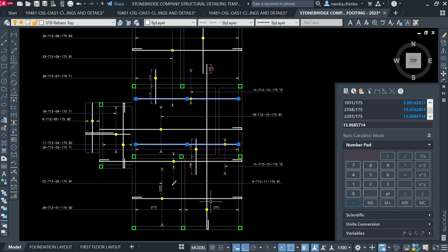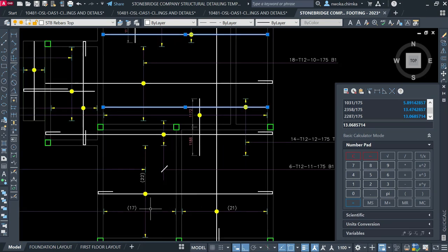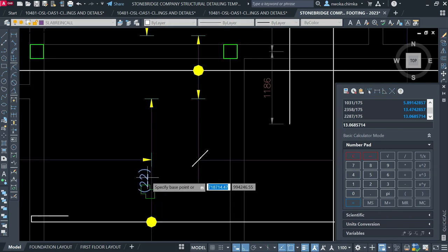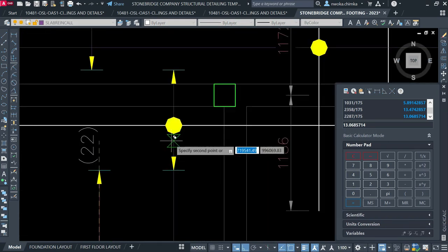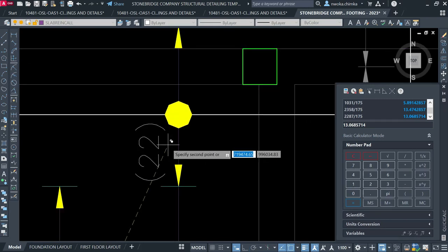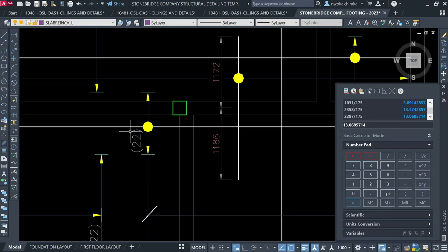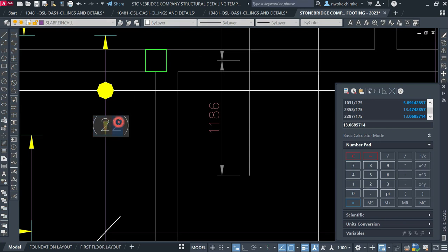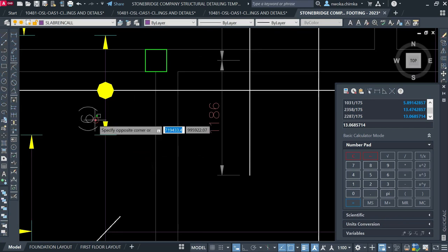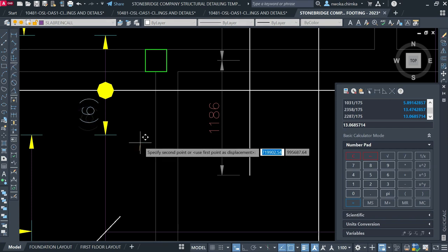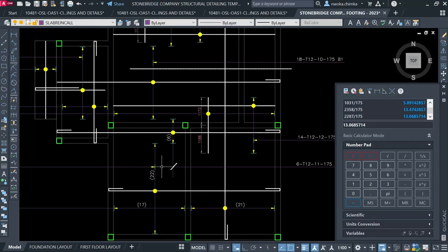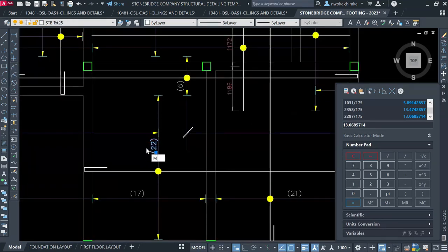So right now let's begin to put in these values, which is the bars running in that area. It's always good to put it around the bars so that it can be read very fast on site. I'll put this one here, and this one says how many numbers, which is 6. So I'll come here and put inside here 6. Okay, I'll put this here and then put this here. That's fine. So again, this other one here, where's the bar? Let me just carry this one down a bit.